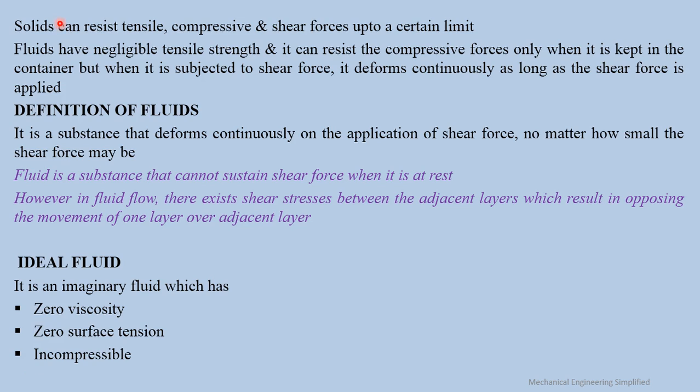Then solids can resist tensile, compressive and shear forces up to a certain limit. And what is that certain limit? It is elastic limit. Fluids have negligible tensile strength, which means fluid cannot resist tensile force. It can resist the compressive forces only when it is kept in a container. But when it is subjected to shear force, what happens? It deforms continuously as long as the shear force is applied.